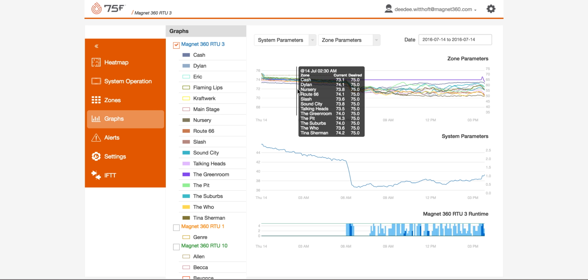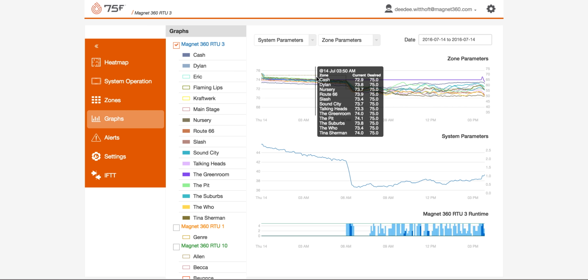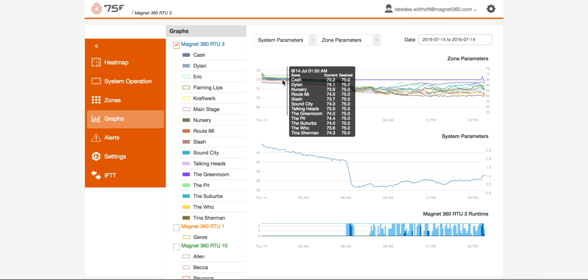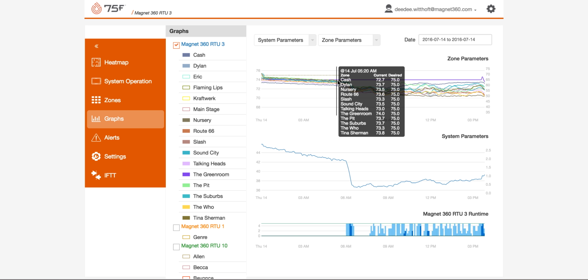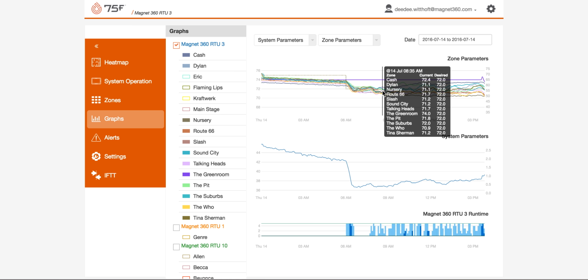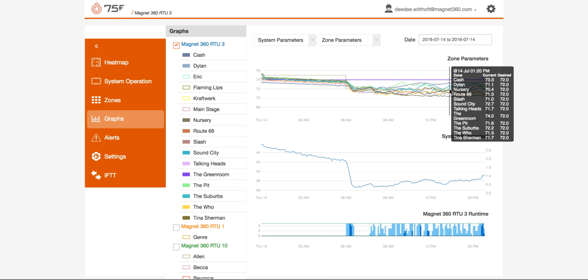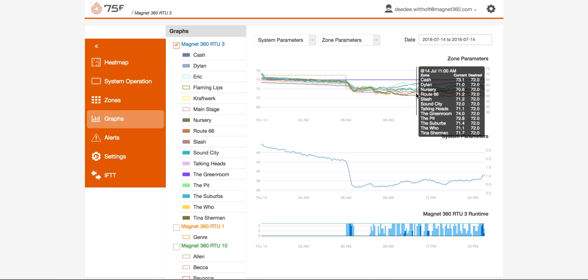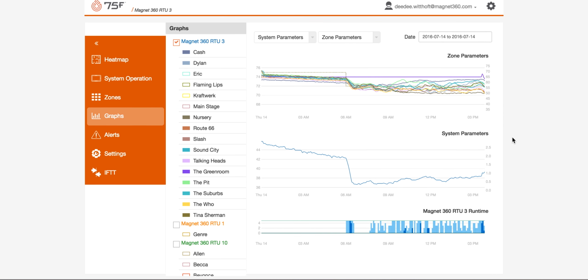So you can see in this graph that this is the point in time where it's going into setback, because the temperature is rising, and it's summertime, so the temperature is going to rise when the system turns off. Then the system turns on, that's when there's cooling in the building, and that's when people are coming back into the building around 9 a.m. here, and you can see that it's lowering the temperature.